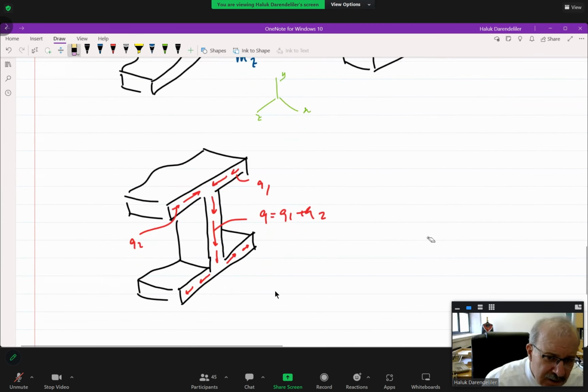The best way is this. You have your shear force on the cross section. We know that our shear force is in this direction, Vy. So in the middle portion, I have the same direction, the direction of the Q is the same with that. Then just determine the others by thinking of a fluid flowing in a channel.